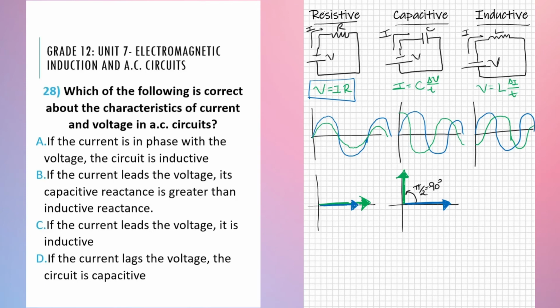How you can represent this in a phasor diagram is simply, again, if our voltage is at this 0-degree angle like so, our voltage is the one in blue and it's at the 0-degree angle, our current will lag behind the voltage. So you usually represent this like so. Our current lags behind the voltage. Again, this is at an angle of pi over 2, or 90 degrees.